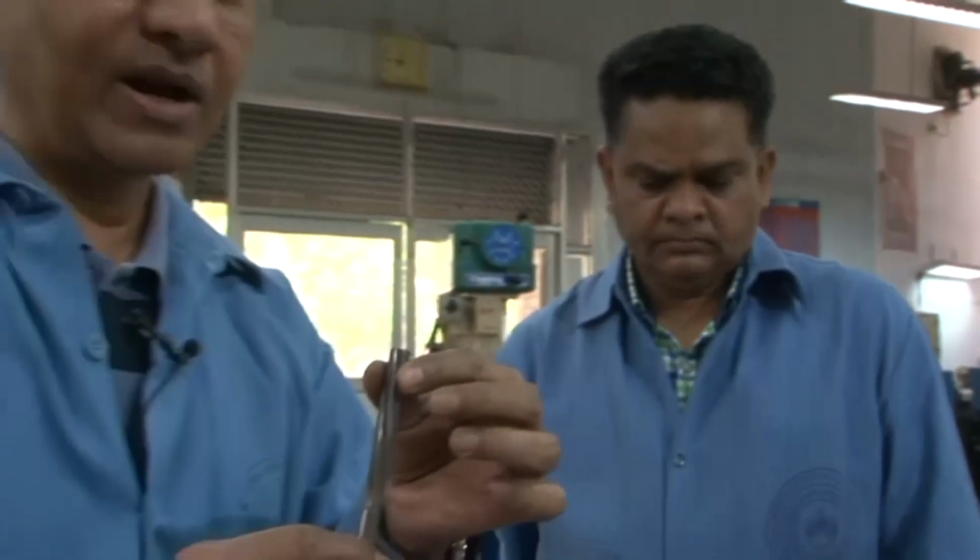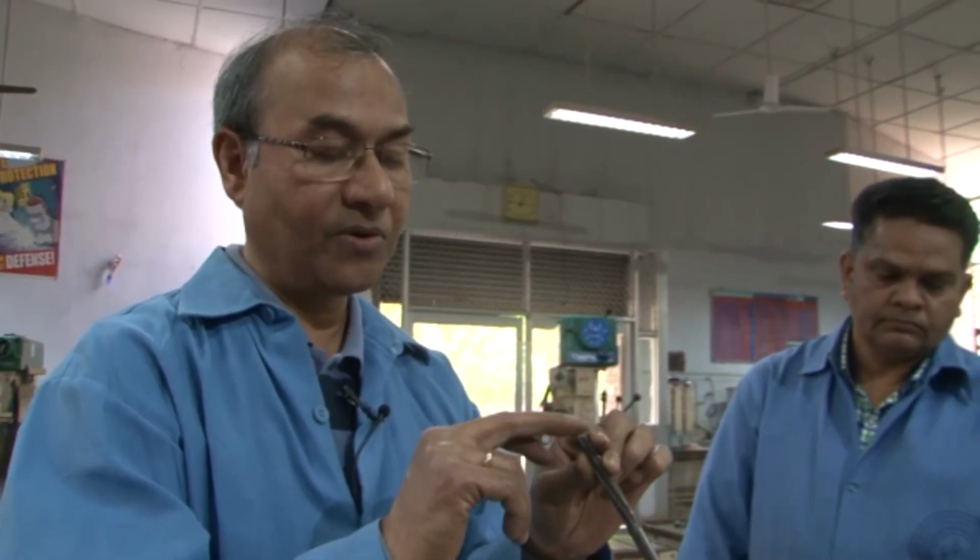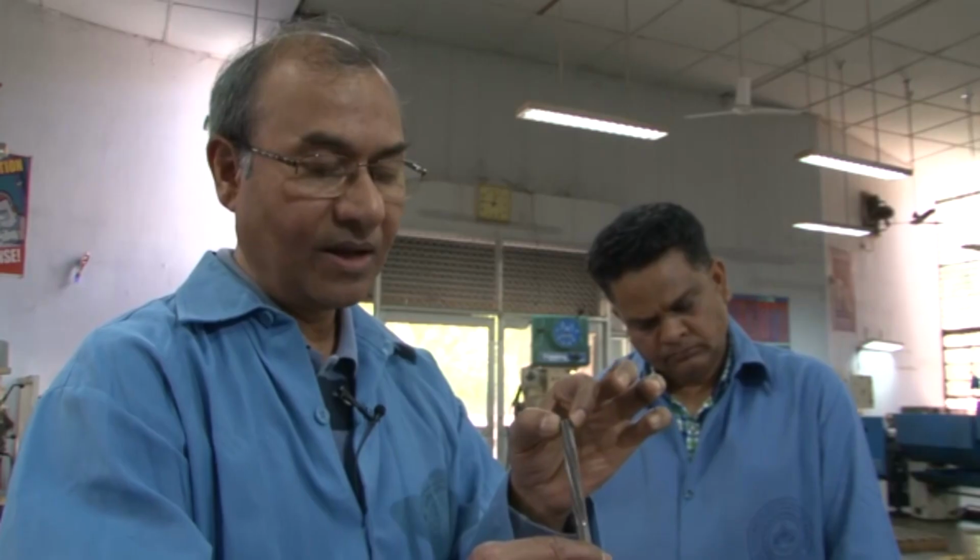Another reason for having an even number is that the force requirement here is not as much as in drilling, because the material removal rate is not high. Therefore, the force balance is very important for the opposite teeth, and only if there is an even number of teeth will the opposite teeth have balanced force. That is another reason why the number of teeth on a reamer is always even. In practice, be it a machine reamer or a hand reamer, the number of teeth will always be even.